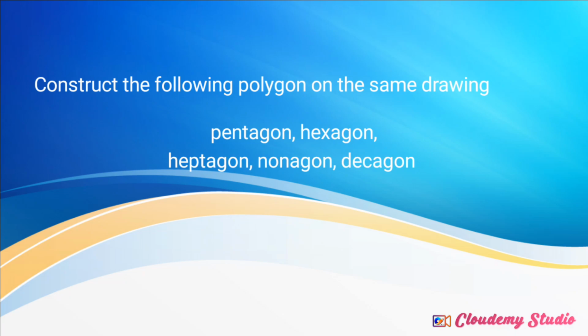And another key point that you have to look for in this type of question is the word construct. When you're asked to construct, we always want to see the markings, the arcs. If you see the arcs, then it means that you constructed. But if you just see the dots, it means you are measuring. So you'll be denied a mark for construction. So always, for construct questions, make sure that you use a pair of compasses to make the arcs, so that the examiner can know you did construct, at least what was asked.